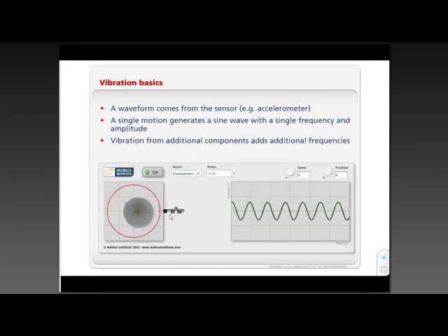Now, we use those on turbines, and we can use those on machines with journal bearings or sleeve bearings. We used to use velocity probes, but we'll focus on accelerometers, and the only difference being we take that accelerometer, mount it on the bearing housing, and because the shaft is trying to move in this circular motion, and because there might be damage to the bearings themselves or all those other things we just mentioned, that vibration all sums together and makes the bearing housing want to move.